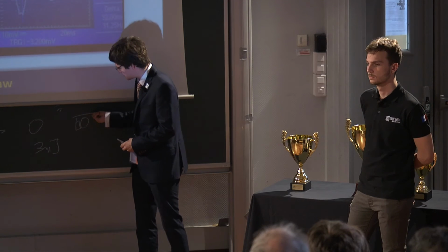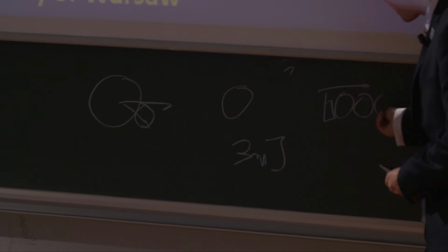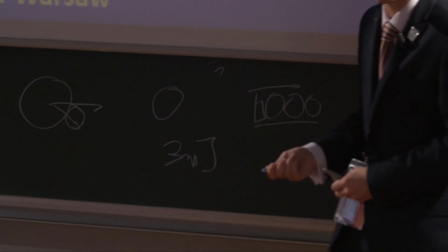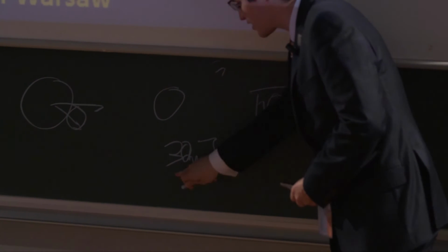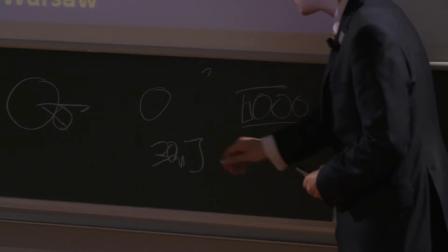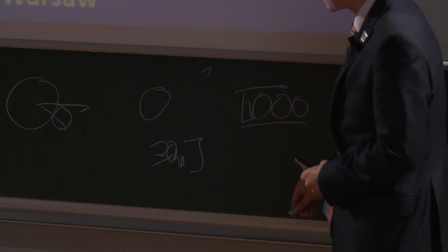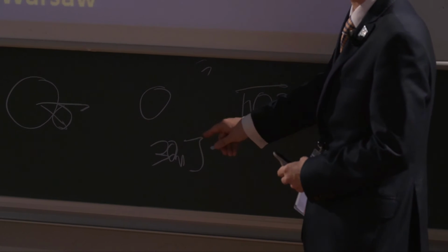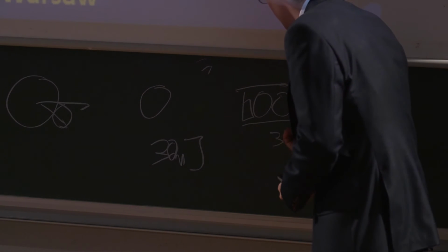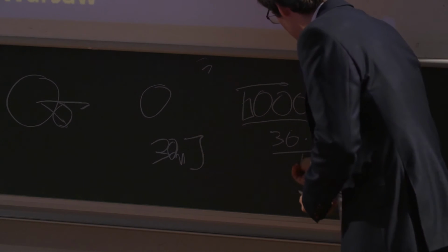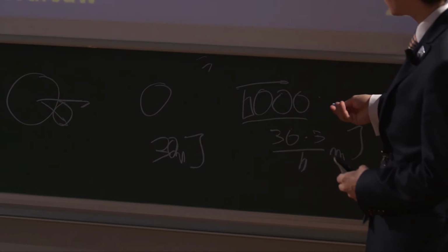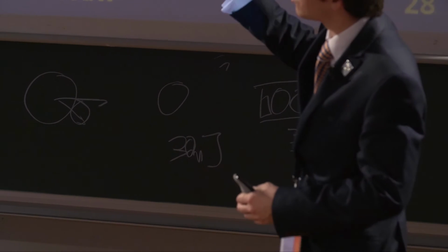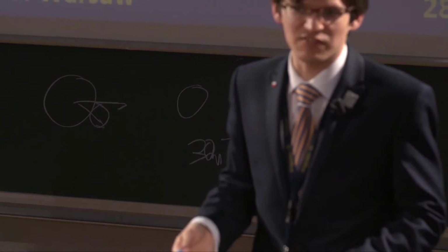During this collision phase, when we have three balls after the setup, there's energy dissipation of 24%. So this 30 millijoules is lost by about three quarters of it. The velocity of the ejected ball can be, depending on the parameters, 1.45 meters per second.